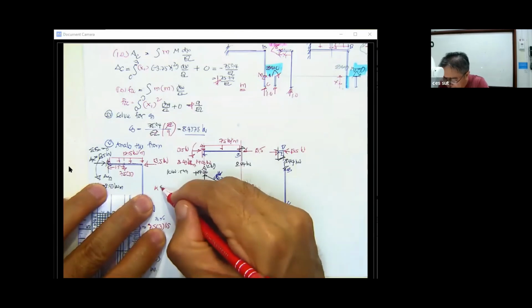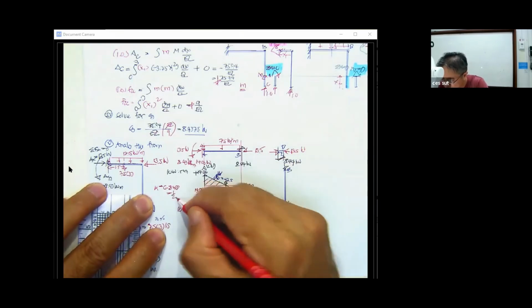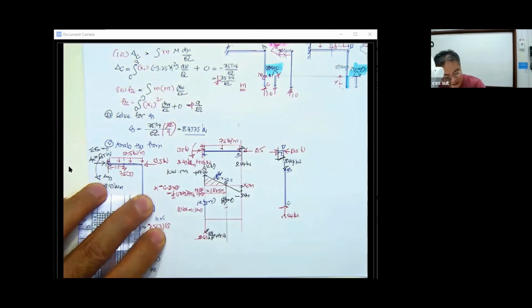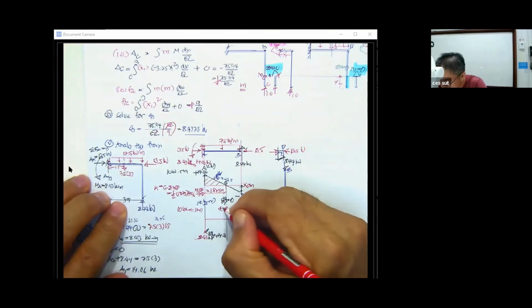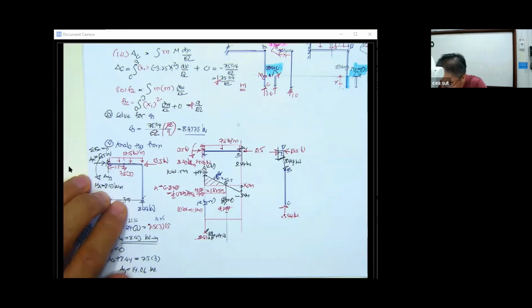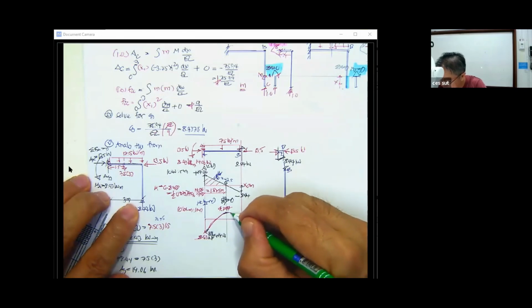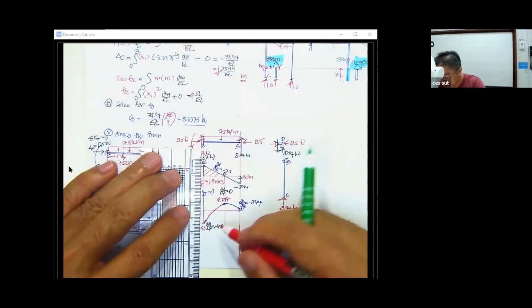Moment here minus the minus 8.43 is going to be equal to this area, 1/2 of 1.875 times 14.06. If you push it into the calculator, it's going to be 4.747, that is going to be half of that, okay, that is going to be 4.746 or 7. Just put this one, and then the curve is going to be something like this, and the rest of this moment is 0. For sure the curve is going to be concave like this. dM by dx is going to be minus 8.44. This is going to be the moment diagram.